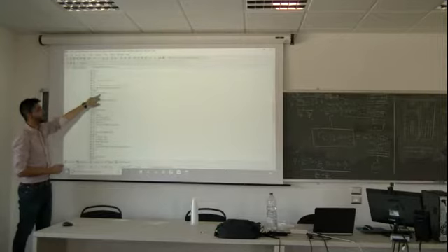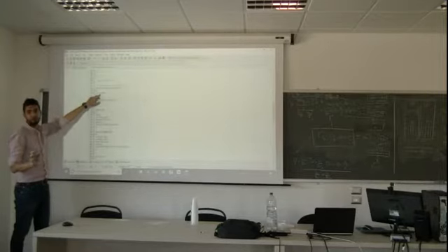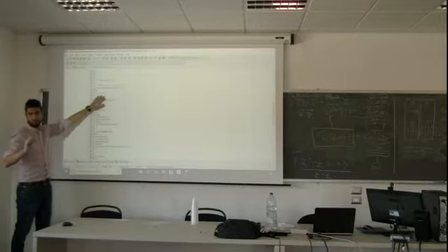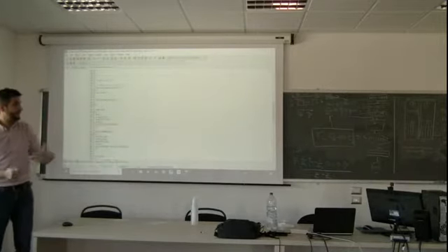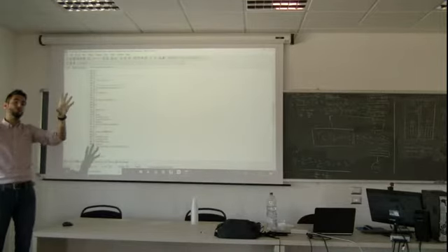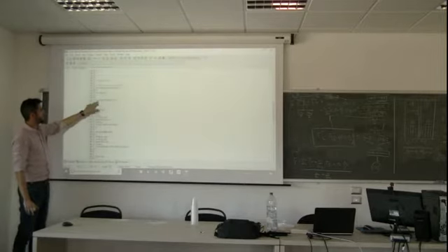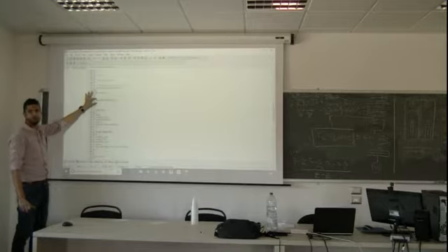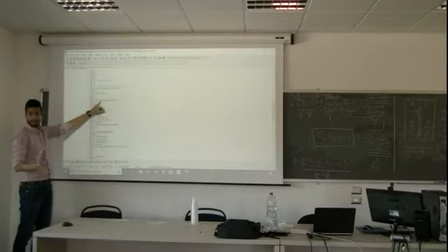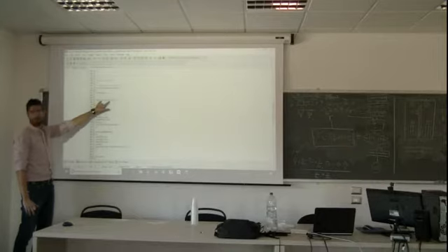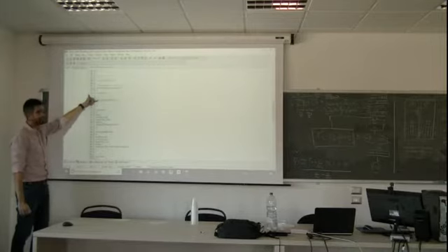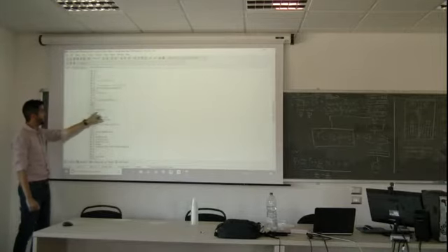Now, the first thing we start with in the iteration is, okay, the error is equal to 0. I need to restart the error. So after the calculations, I can say, okay, what is the maximum error between assumption and solution? I restart this. Now, we start with the important part: the geometrical loop. Now I have to explore all my domain, from I equal to 0 until I is below or equal to n plus n, I plus plus. So now here the code will start with I equal to 0.